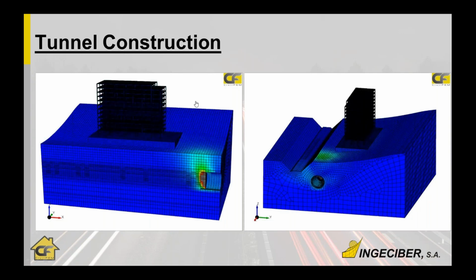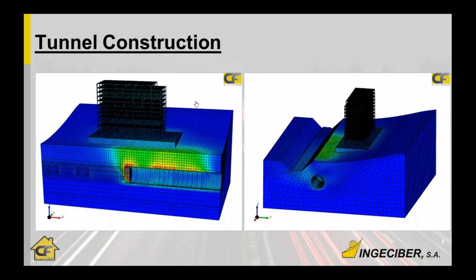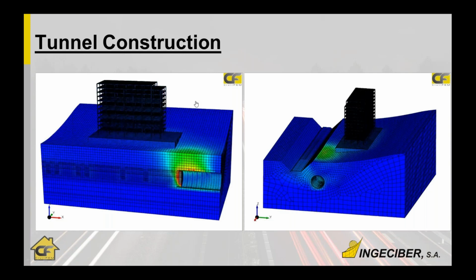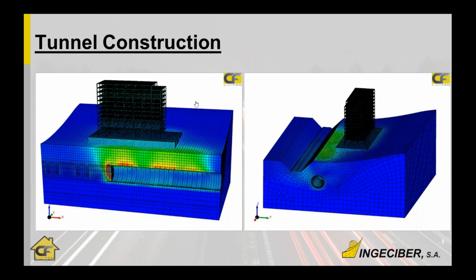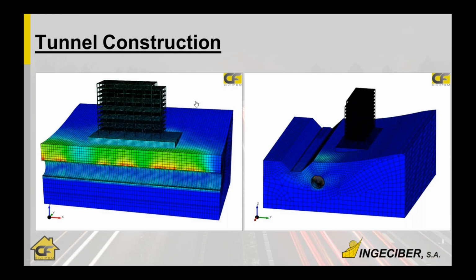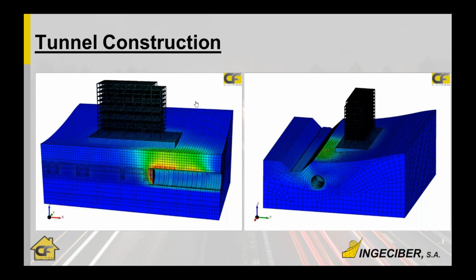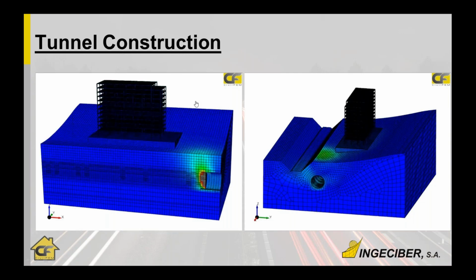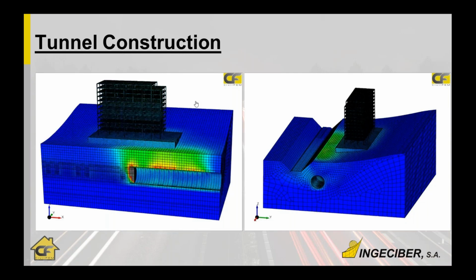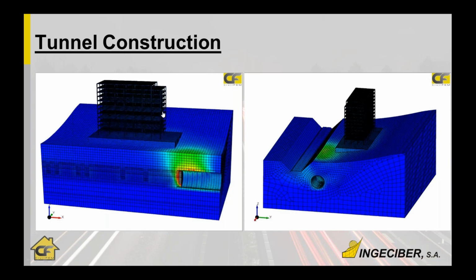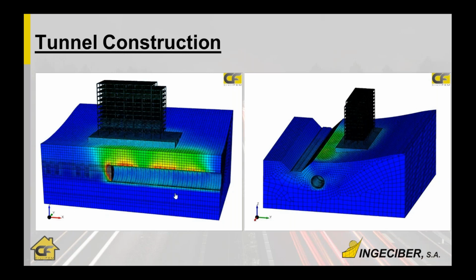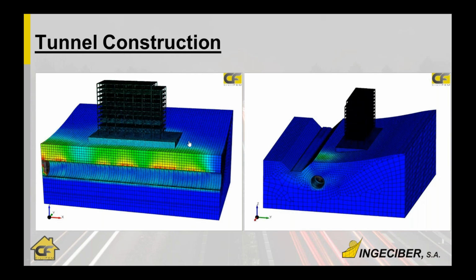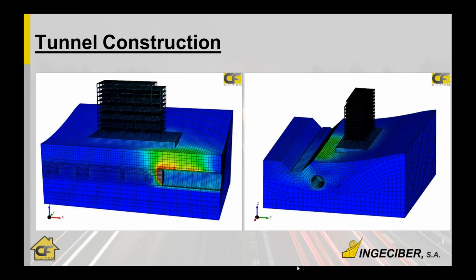So in CivilFEM, you have a very good tool to analyze in detail, with nonlinear analysis, the fiber reinforced concrete behavior for tunneling and for these ring segments, ensuring safety, after checking CivilFEM results with the beam test and the lining segment test, comparing the real tests with CivilFEM results. So you can perform full models with those properties, generating the rings here, and calculate the global behavior of the excavation process. So well, this is the first example.